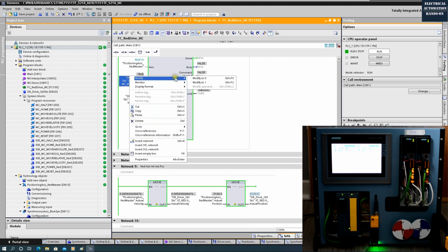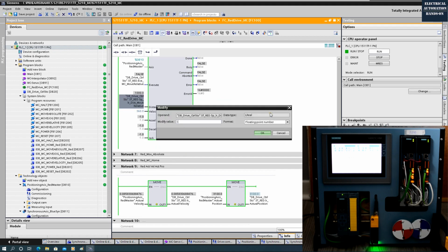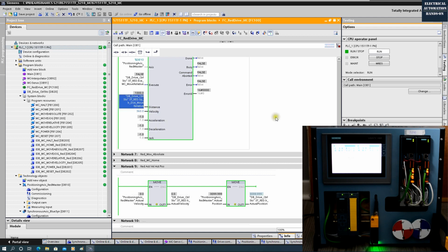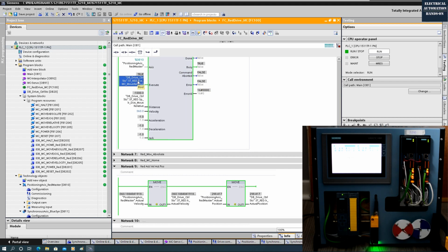Okay, 3100. So for moving backward, we can set this distance to negative. For example, let's move negative 1000. So we can trigger. Okay, so we will see this command, that's the trigger signal. Once the drive gets here, it will not keep triggering. It is only waiting for the rising edge. So it gets 2100 again. Let's trigger again. Then next time it should get 1100. Okay, 1100. Let's trigger again, go back to 100, backward.